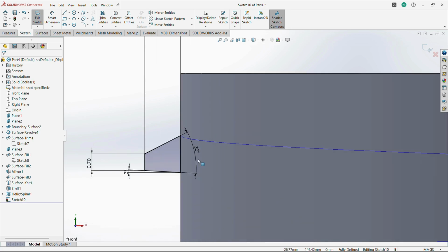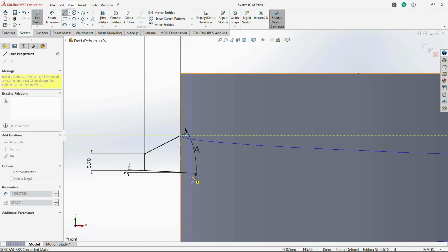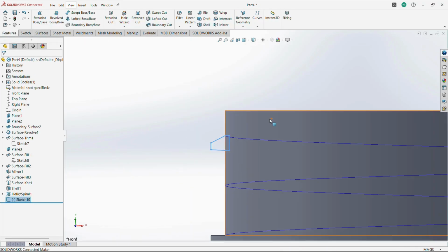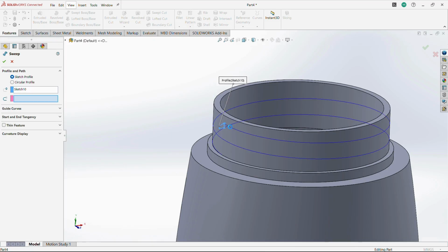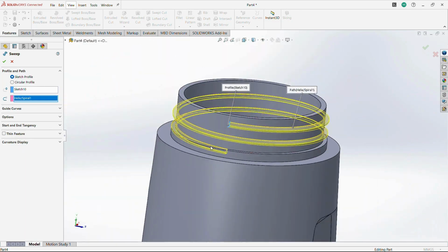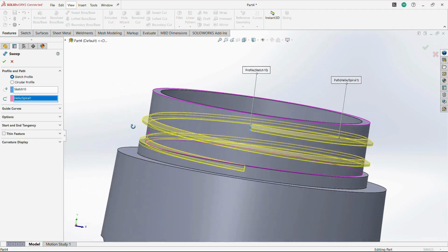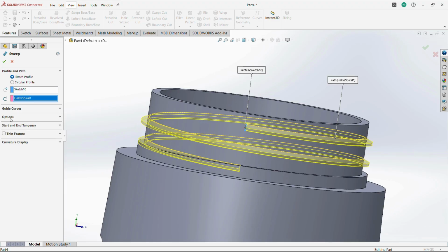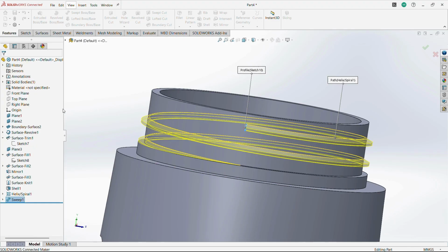Next thing we need to do is, if you have a trapezoid profile and draw it from this angular circular edge, it is basically not created properly. That's why we extend the small projections randomly. Why? Then only the solid body is merged with the default body. Now choose the sweep option. Then select these profiles. If you want to merge it to the opposite section, choose aligned with end faces. It is automatically merged with the bottom of this face area.